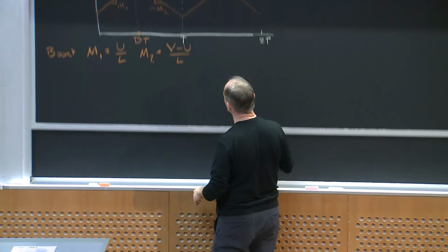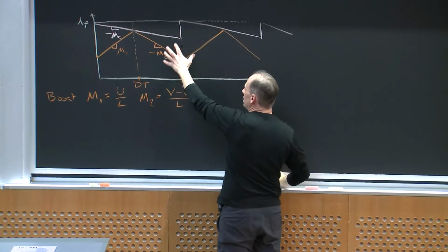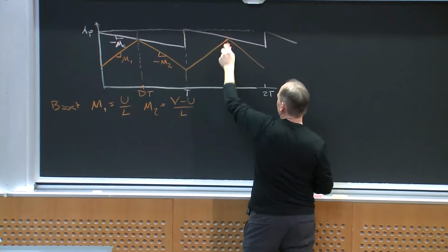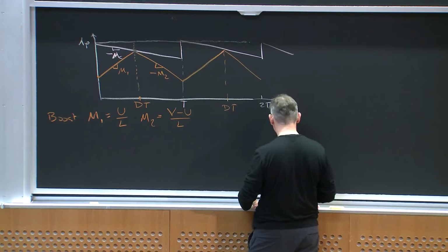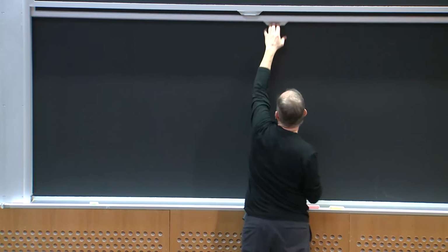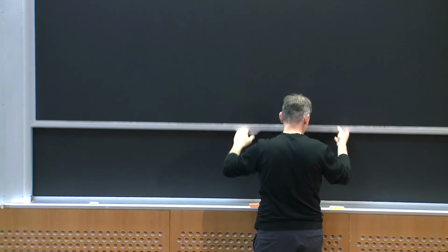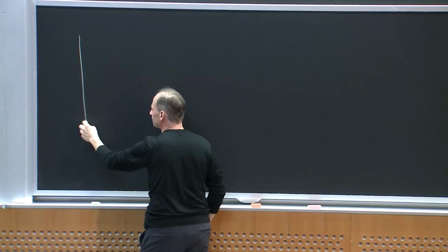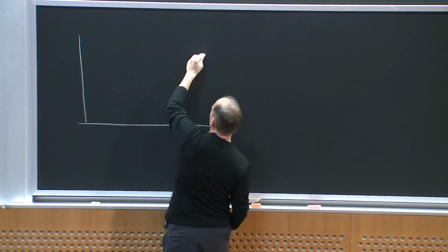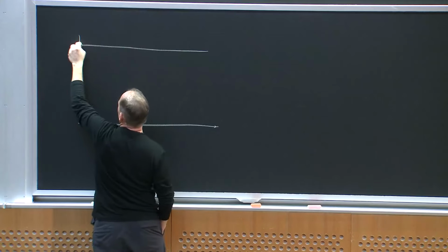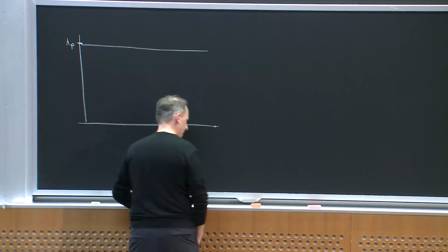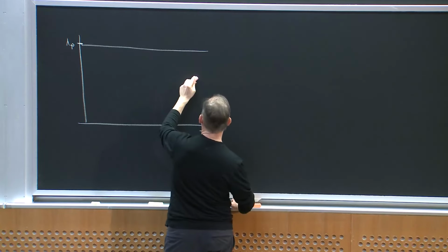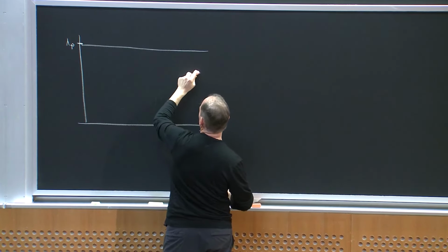And so here's the idea. This picture I drew is actually a periodic steady state picture, right? I used capital D here. I'm assuming it does something every cycle, capital T, okay? Let's just draw a slightly better picture for purposes of analysis. Okay, so here we go. Here's my waveform. Here's my peak current, high peak, right? And then I have my so-called compensating ramp, which falls with some slope minus MC.